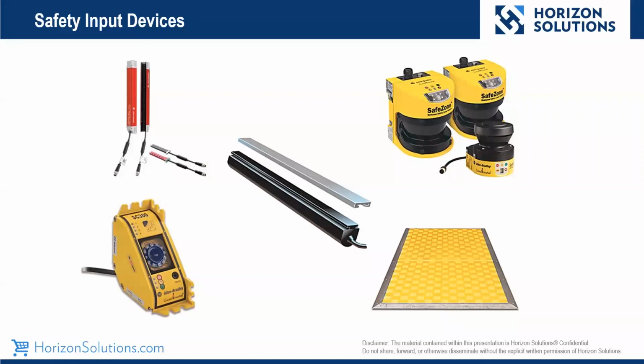This is because these area scanners have a 40 or 70 millimeter object resolution for leg or torso detection. If we can only detect a leg or the torso, we cannot reliably determine how close the hand or the arm or any other part of the body is to that actual hazard. Therefore, we have to stop the hazard sooner.